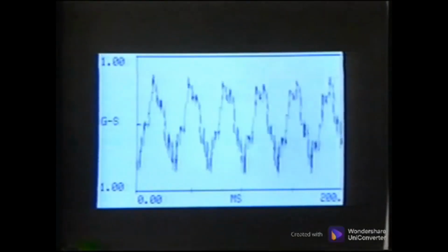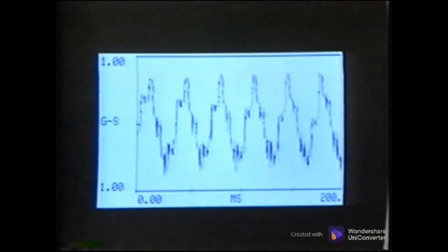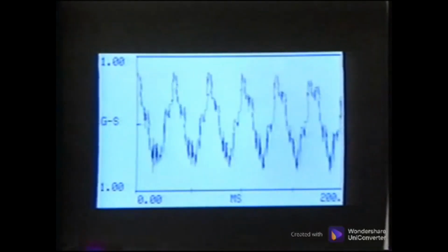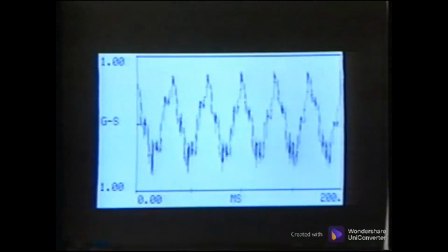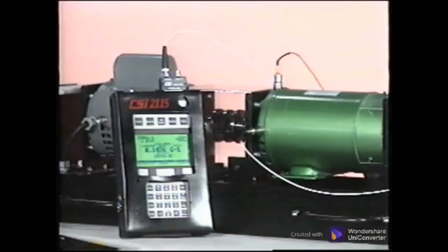The waveform in acceleration units is more complex due to the energy from high-frequency impacting riding on the 1 times sine wave due to the unbalance. But the waveform is still dominated by the single frequency due to the unbalance. Periodic repetitive waveforms can be at the turning speed of the shaft or its multiples.